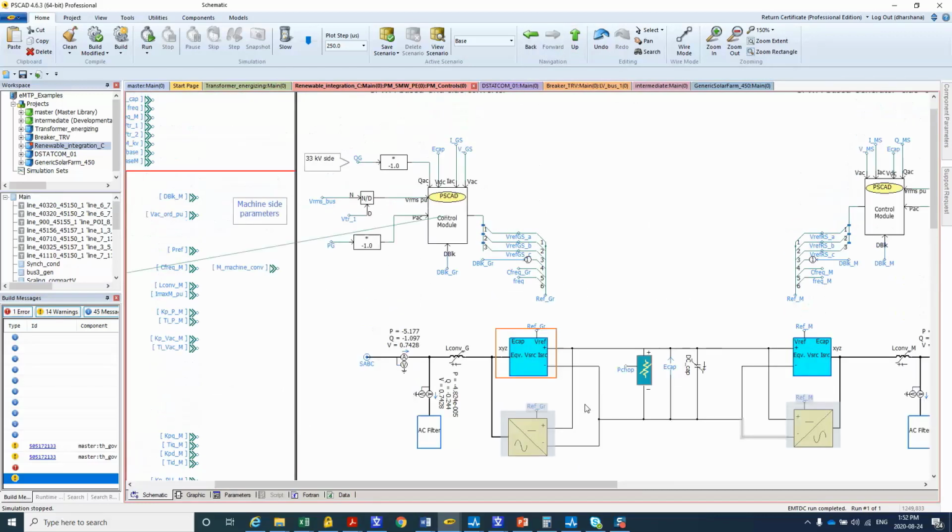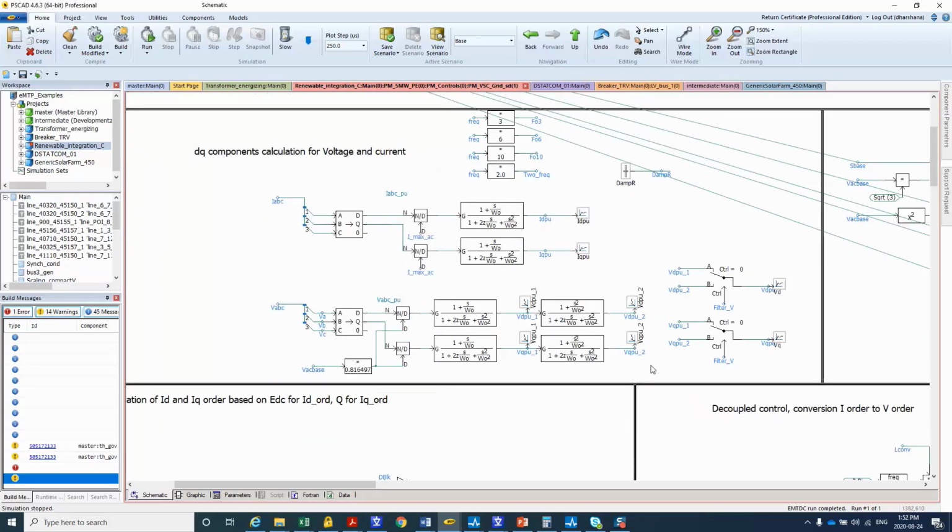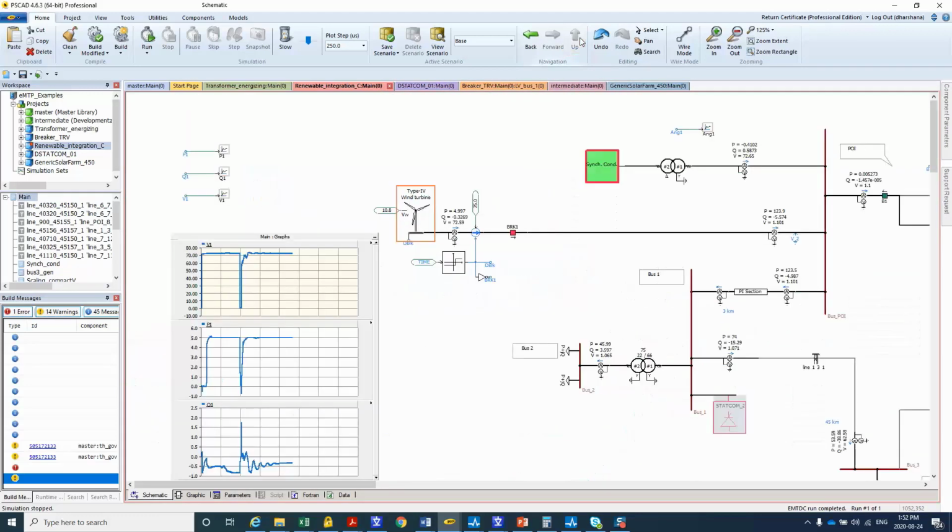And then if you go to the controls of the power electronics, once again, controls, protection functions, limiting functions, ramping functions are all modeled in detail, closely resembling the actual design. Of course, in this example, I am using a generic model of a wind turbine. When you do more specific studies, the model of the wind turbine would come from the equipment supplier.